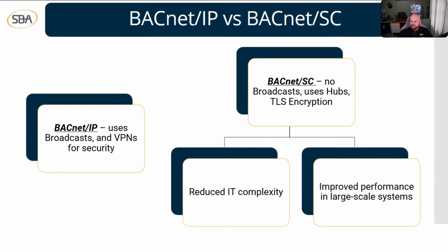All right, so now we're going to take a look at some differences between BACnet over IP and BACnet Secure Connect. And as you can see from the slide, there's not a lot here in the means of BACnet over IP, but let's go through it real quick. So BACnet over IP uses broadcasts and VPNs for security.